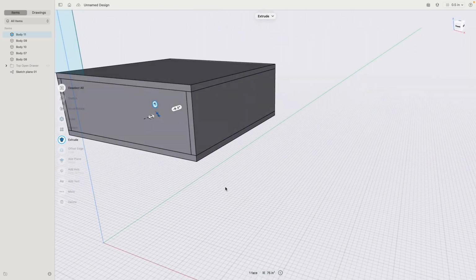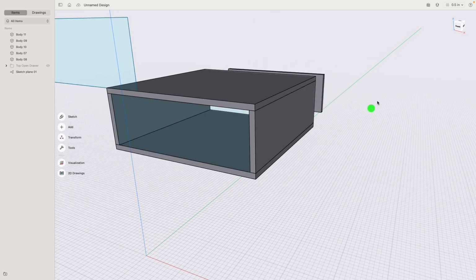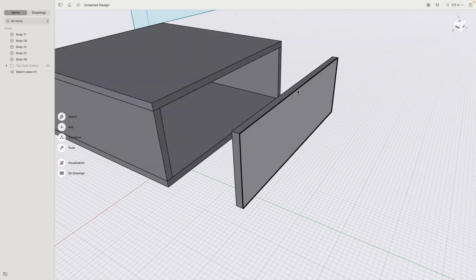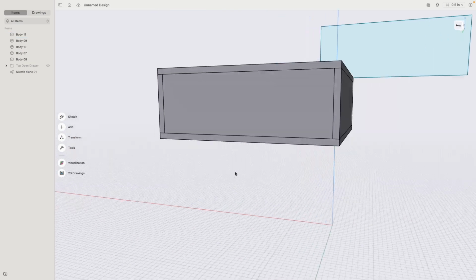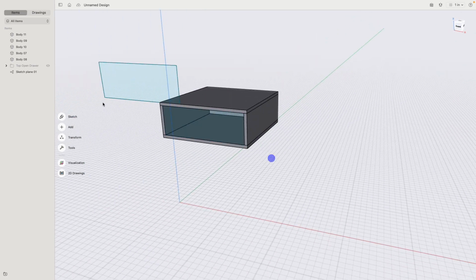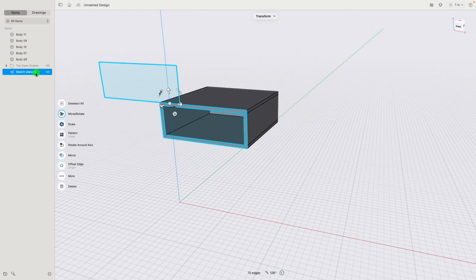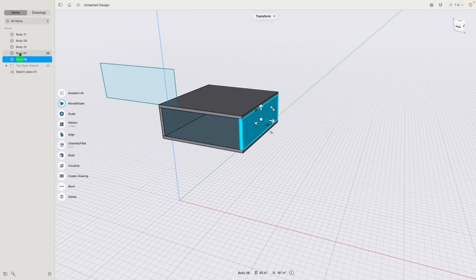But now this back plate is sitting actually at the wrong position. So let's double click, move this back. Let me show you something. We can then select this edge, and simply say align, and it moves this part right into the position. Beautiful. So you see, it didn't really matter that our initial sketch with the back plate was actually at the front. There we are. Very good.